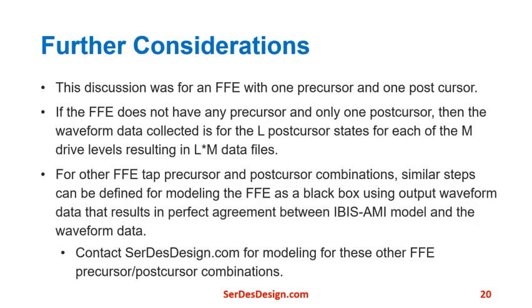Here are items for further consideration. This discussion was for an FFE with one precursor and one postcursor. If the FFE does not have any precursor and only one postcursor, then the waveform data collected is for the L postcursor states for each of the M drive levels, resulting in L times M data files.